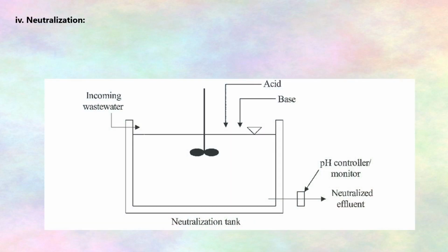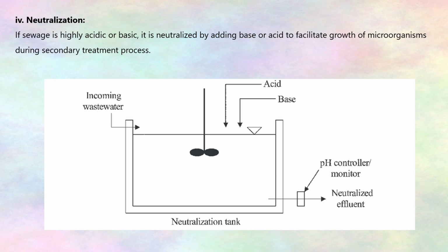The next step is called neutralization. In this step, if sewage is highly acidic or basic, it is neutralized by adding base or acid to facilitate the growth of microorganisms during the secondary treatment process.